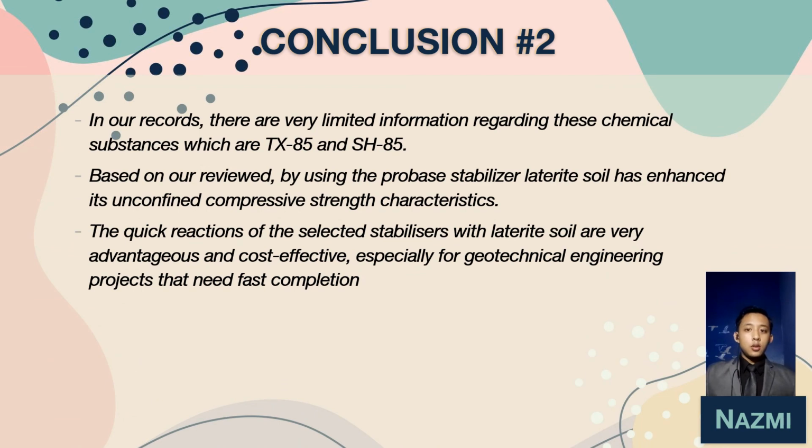For the second conclusion, there is very limited information regarding these chemicals, which are TX85 and SH85. Based on our review, by using the proper stabilizer, it has enhanced the unconfined compressive strength characteristic. The quick reactions of the selected stabilizers with laterite soil are very advantageous and cost effective, especially for geotechnical engineering projects that need fast completion.